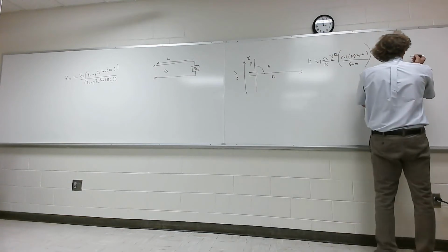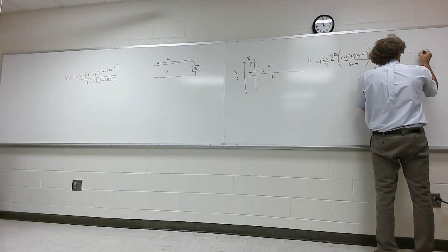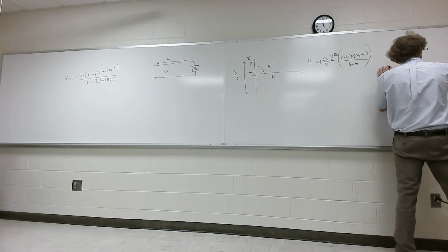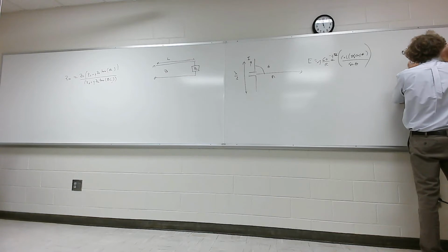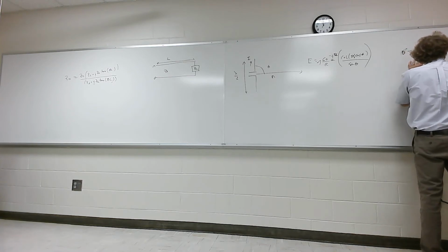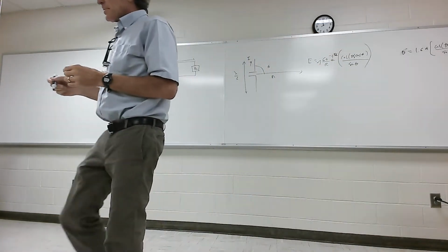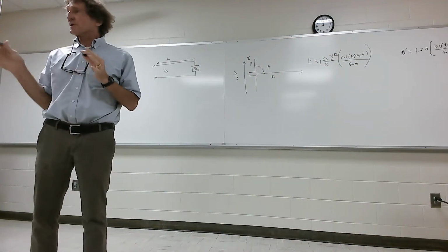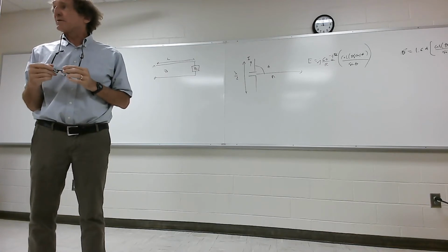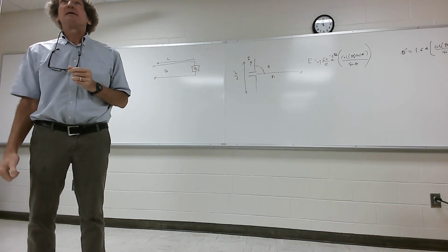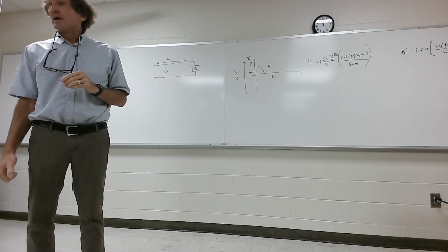And I'll give you the gain of a half wave, which is 1.64, or really directivity, but directivity and gain are pretty much interchangeable. And then it's going to be times the cosine of pi over 2 cosine of theta over the sine of theta squared. All right, so that would be the directivity. Now, I won't give you information about the short dipole, but any kind of loop I would provide you information for gain, or really for the H field or E field from a small loop.